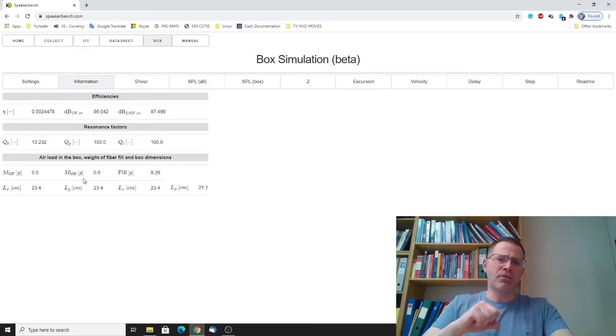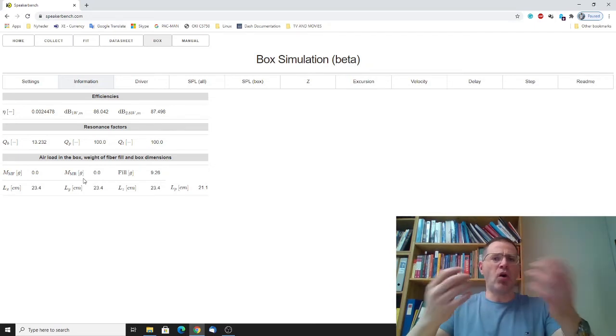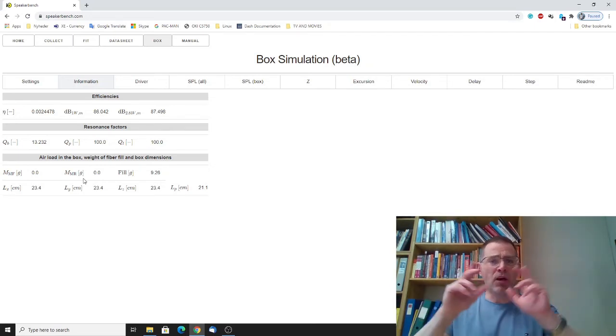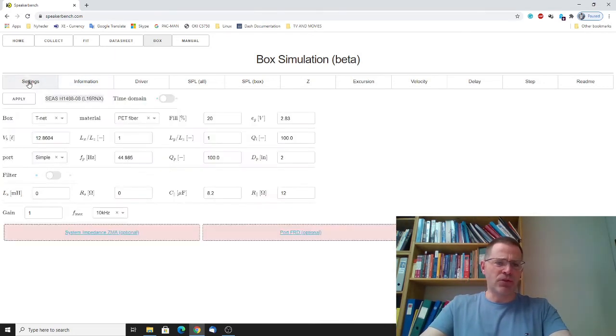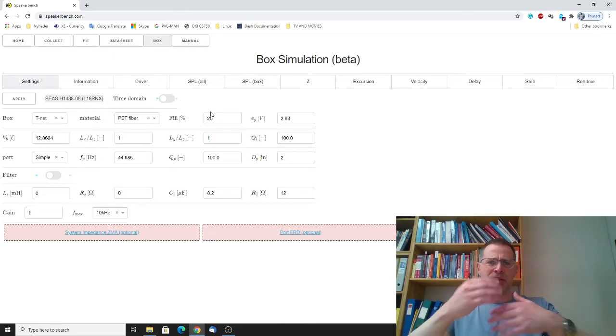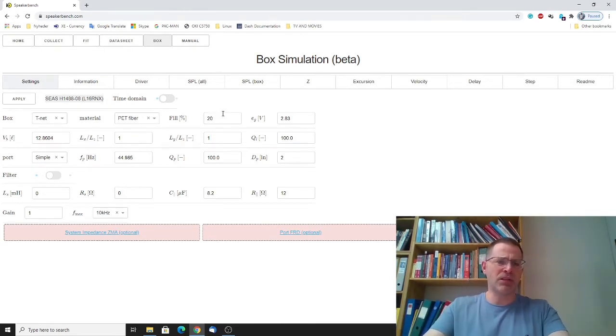But obviously, if you add damping material, it cannot all be in that optimal place in the middle of the box. So the simulation exaggerates, and in practice you would have to add more damping material. But that's why we chose just some kind of percentage. It's a little bit abstract, and you get a percentage to work with.